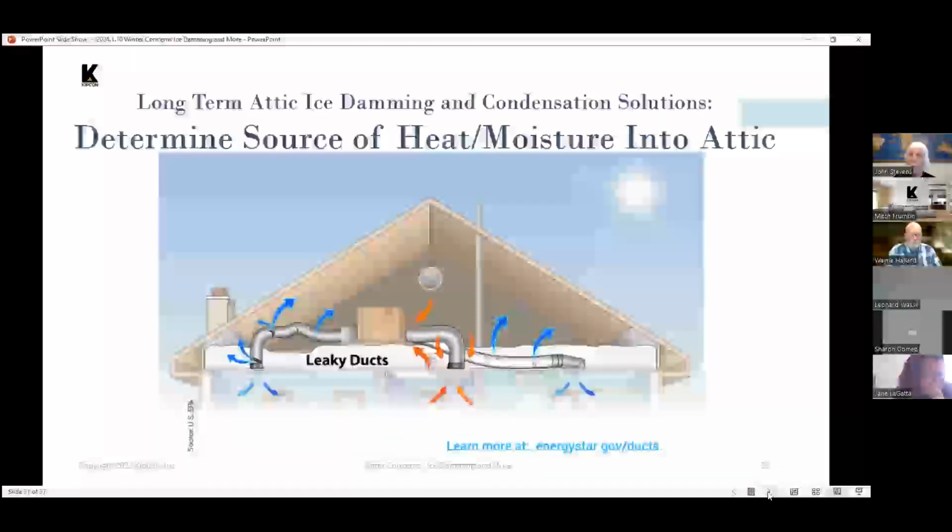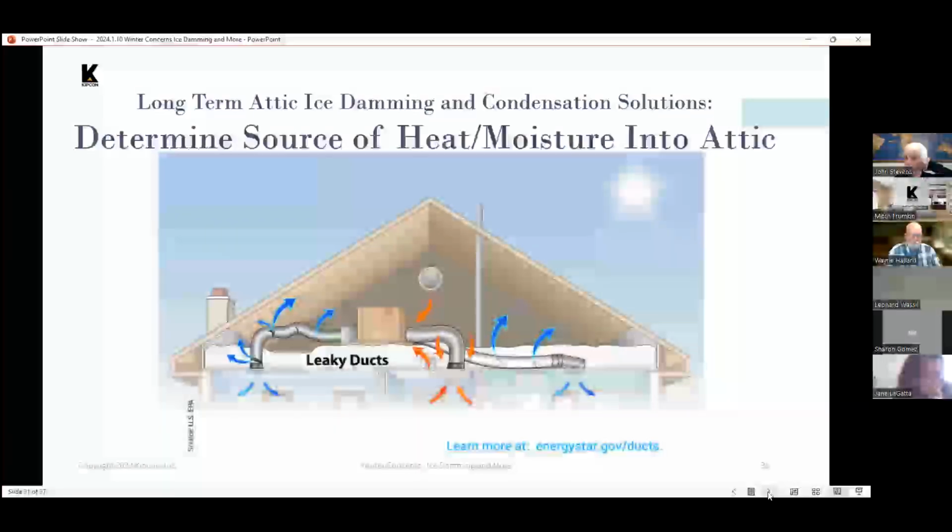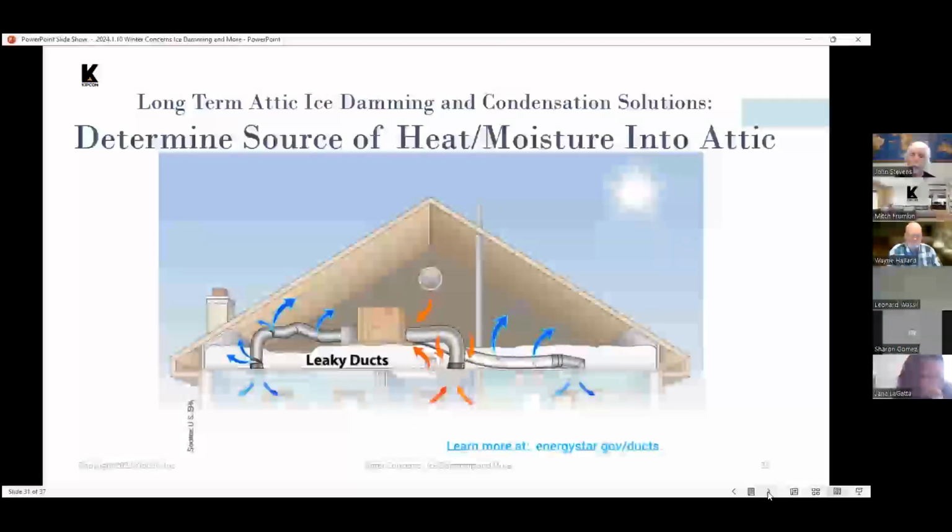And then the second step is to add as much ventilation as possible. But also, if you have ducts in the attic, those should be insulated. It's more common today to see what are called flexible ducts, which are insulated. But you also want to make sure that there's no leaks coming out of those, particularly where they join fittings and so forth, or they're spliced in the attic. Make sure those are taped off so air is not leaking out of those and putting warm air into the attic space.